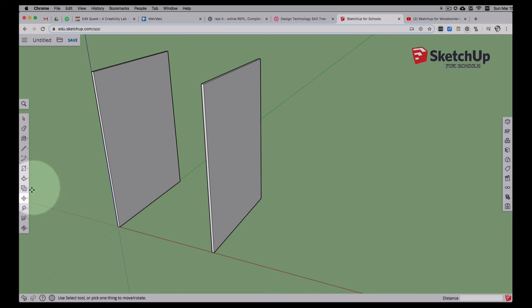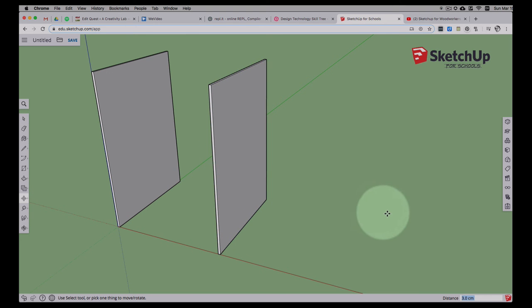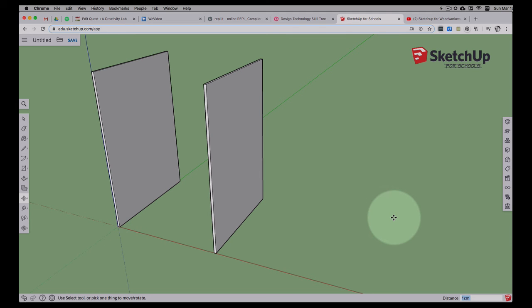But if I take my tape measure and I check this corner, it's this corner to this outside corner that's 50 because I dragged from that face. Remember, I clicked this face here and dragged, and that means that this face here is at that measure point that I typed in. So I actually need this to be at 51. So let's move it again. Move it on this axis, and then we'll type 1 centimeter. And if we go back and measure now from this inside to this inside, we have an exact 50 centimeters.